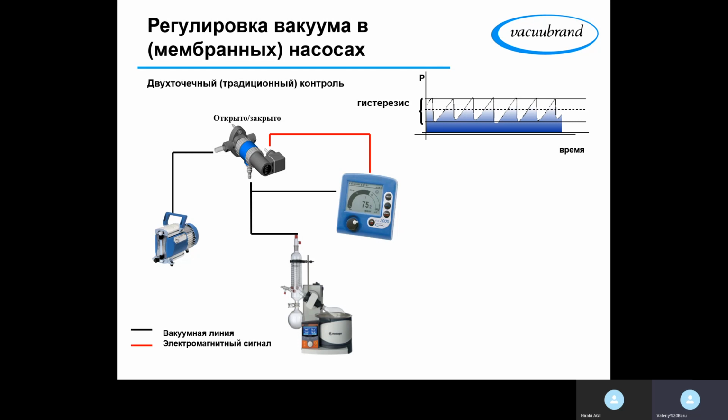But if we're talking about distillation, which occurs very often in reactors, so when we're talking about the distillation of a certain product that we want to get off the system, then it is a problem, especially if the product is a sticky one, or maybe a very expensive one, and so on. So we want to condense all our product in the receiving flask that is not on the outlet of the vacuum pump, but is in our system, right behind the reflux divider, for example. Okay, is that clear?